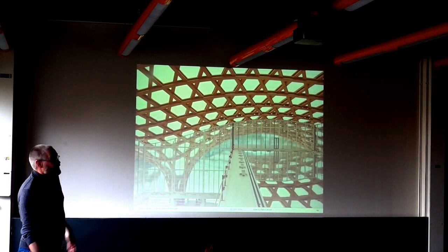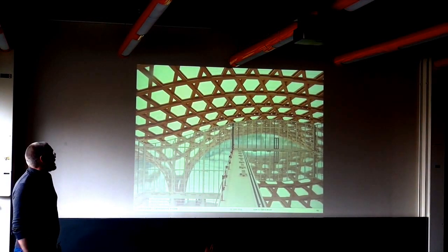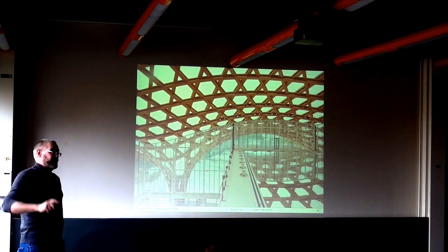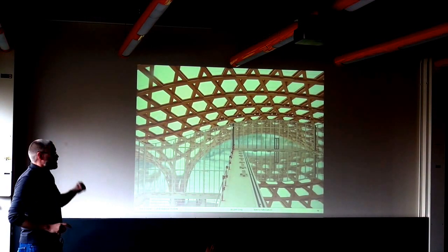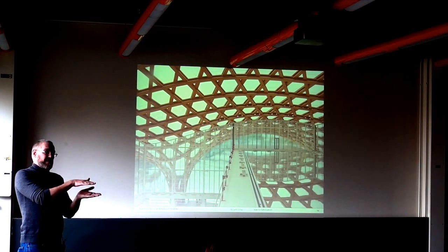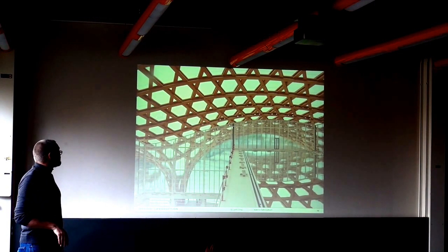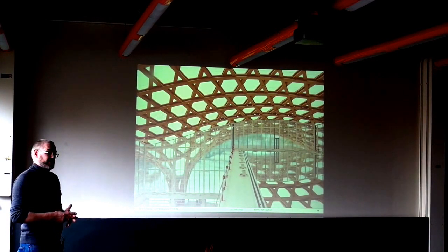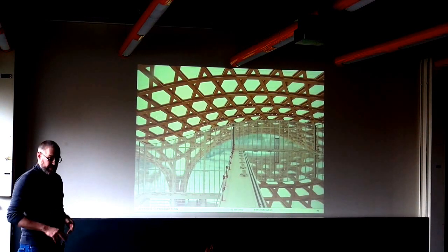So this is, I mean, you've seen this picture already. This is what it looks like. In the end, there's 3 directions of beams, and you have 2 parallel girders running in each direction with shear blocks in between so that you get a stiff girder. And you always have 4 beams crossing in one point, 2 directions.